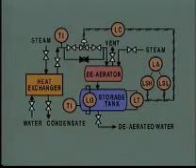When the components in the system are checked, the problem turns out to be a faulty level transmitter that's sending a false high-level signal to the rest of the components in the control system. In this case, the alarm alerted us to a problem early enough that we were able to locate the problem before it had a major effect on the operation of the system.